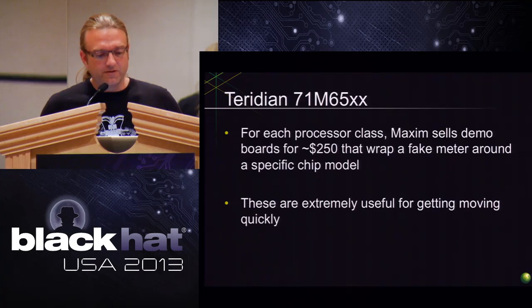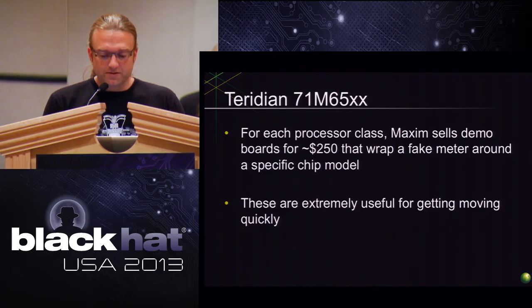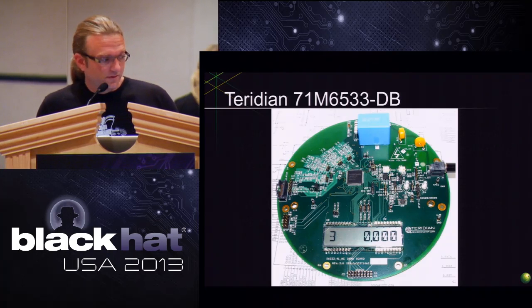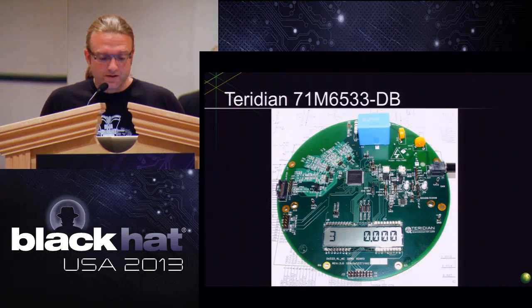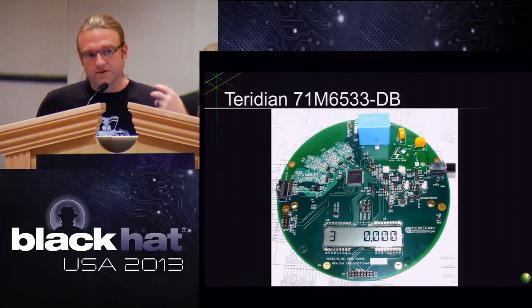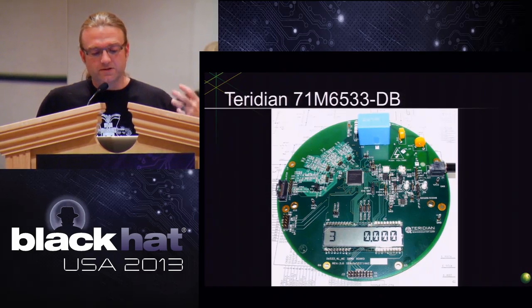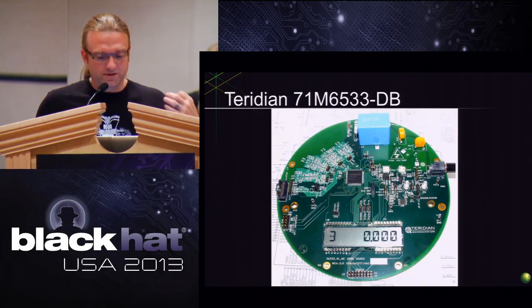So then if you have a specific target you're looking at, you at least know what reference they started with. And you can look at the board, which here's a demo board right here. It's the one we're playing with today. You can start looking at the board and all the specs that come with it and pretty quickly figure out, this is how I physically put the chip into debug mode, this is how I enable JTAG if it's been blown. It's much easier than just starting blind.